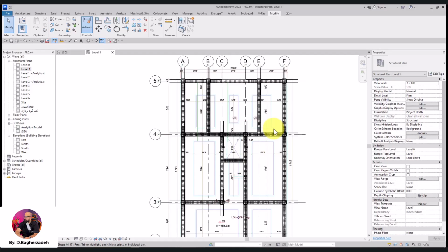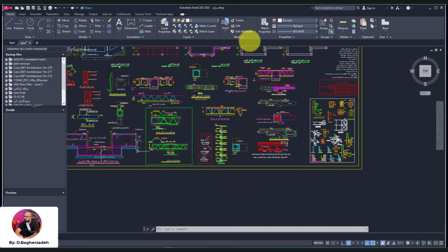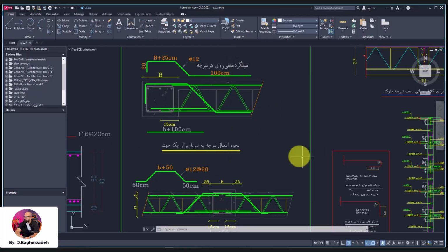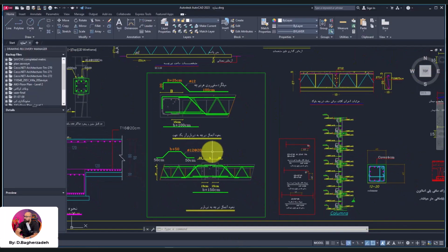As you're aware, we have completed the reinforcing armatures of the slab, or the first level actually. And as you can see, reinforcing beams is done. In the continuation, we're gonna add some beams and also some panels to complete the floor, adding molds, assigning phases, and then concrete casting and reinforcing armatures, this way.